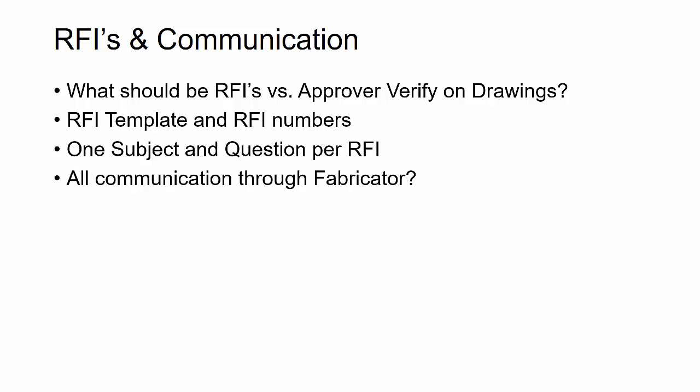Now, you have to be careful about writing it too short or too generic or too simple. Sometimes there's an art form to writing RFIs: if you write something too generically, or if you don't lead toward the answer that you're looking for... I usually write RFIs that are more clarifications, unless I straight out don't know what to do. But I'm guiding and providing all the detail that I need in order to get exactly the answer I want. I've seen some detailers write one-liner RFIs, and then they get a response back where the engineer didn't know exactly what you were asking, and so they gave a fairly generic response, and then you have to follow up with another RFI, which causes delays.